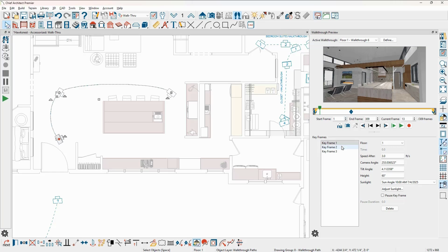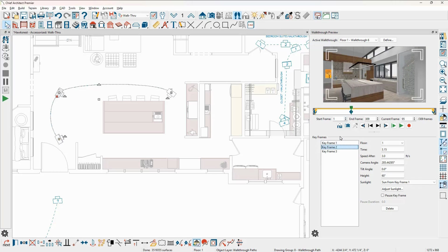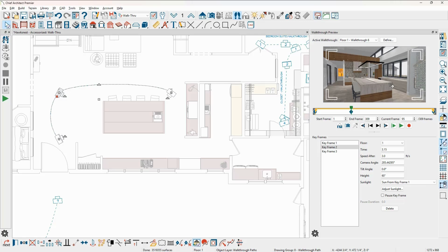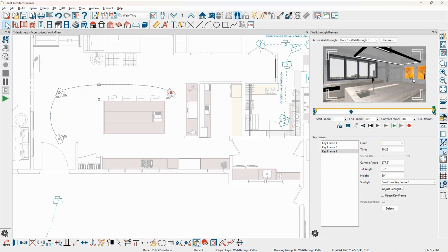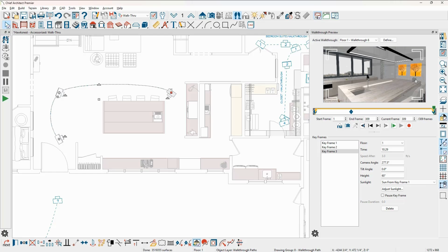Let's double click on keyframe number 2 here. And notice how I get the framing of the scene in with the outside definition, and then my camera changes to the dolly. I can adjust that camera, and again, double click on keyframe number 3. I get the outline surrounding the scene. My camera changes to a dolly, and I can make the adjustment.